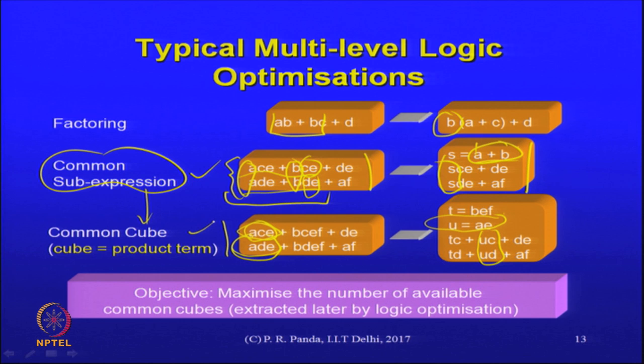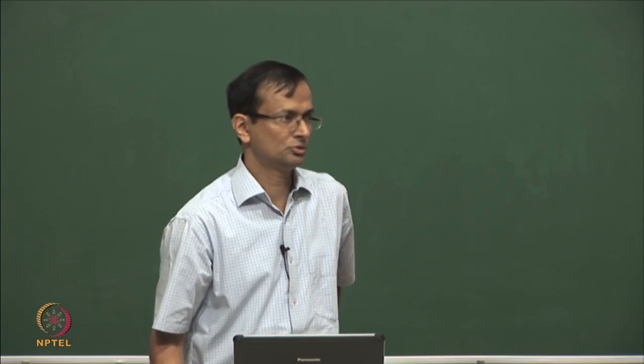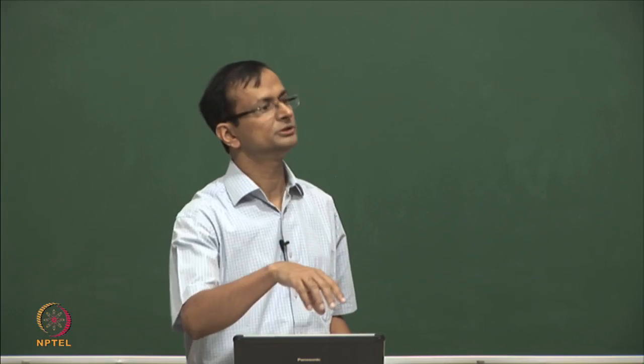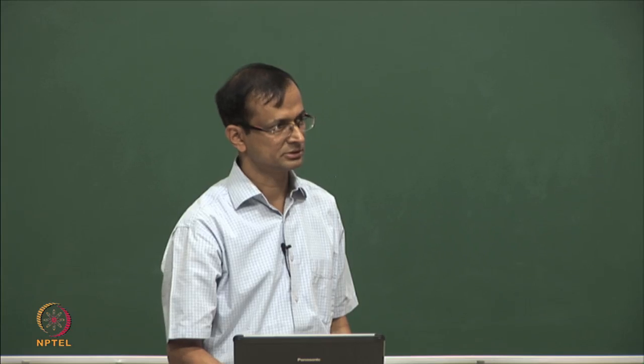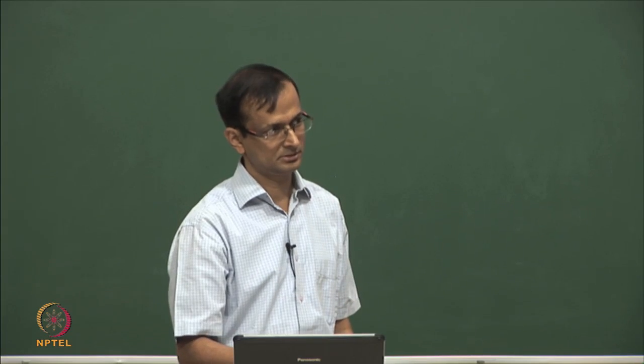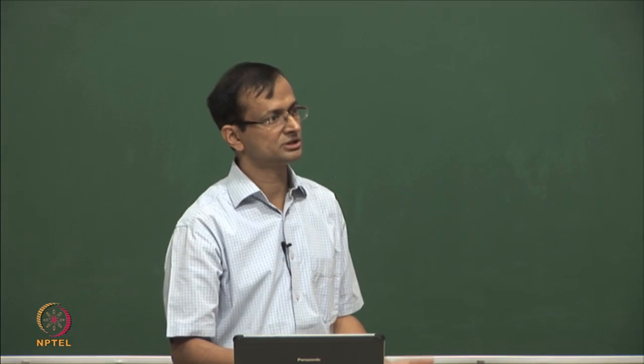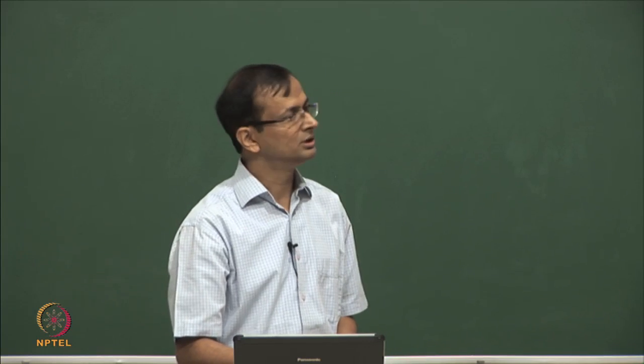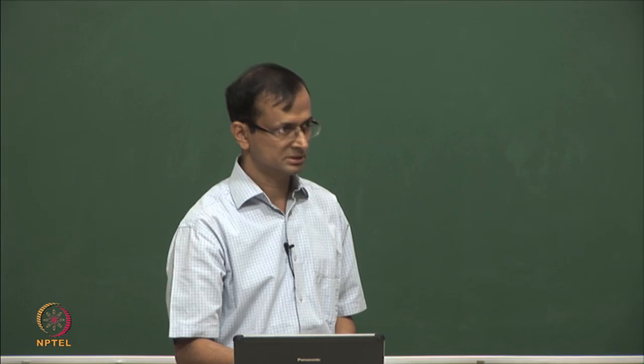Sir, why do we do this common cube actually if we have common subexpression? No. If you have common subexpression, then you don't do common cube. But you could do common cube and not do common subexpression, because that is more difficult. It is still a reasonable logic synthesis tool that would do common cube, not necessarily common subexpression.